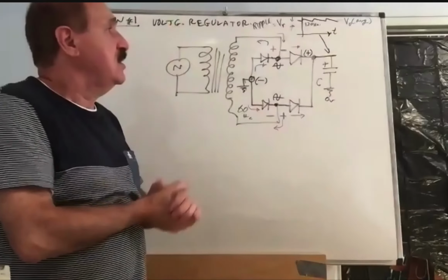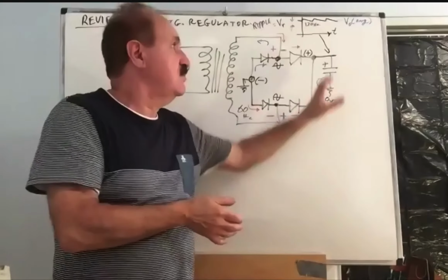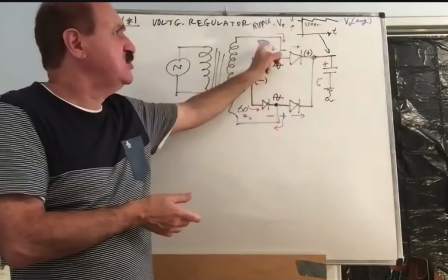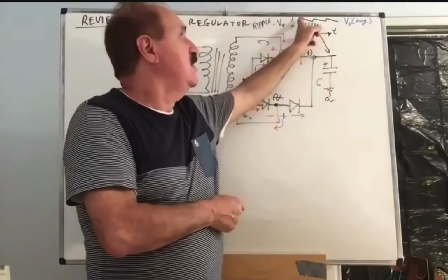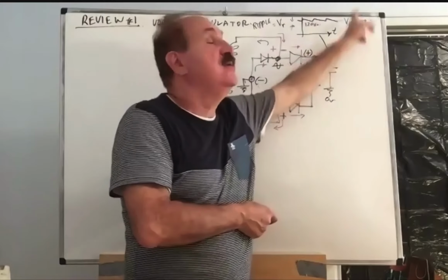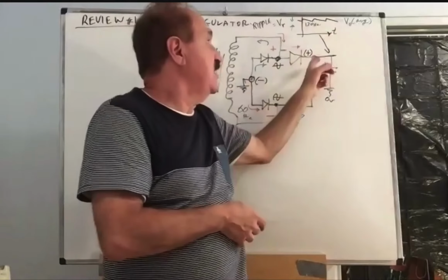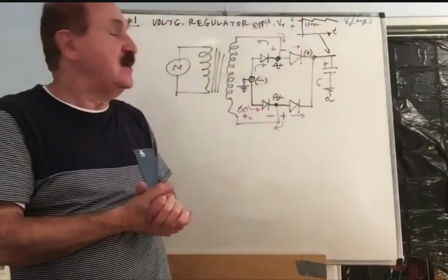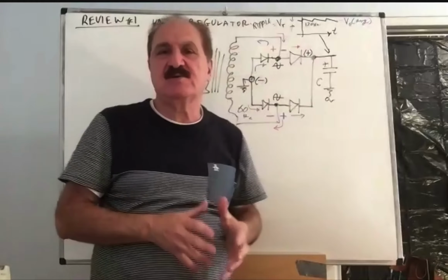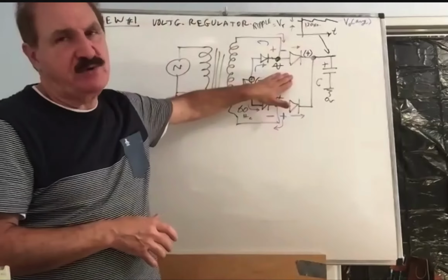So this part completes the AC to DC conversion. A capacitor and bridge rectifier, and that is the popular one. You can do this with a single diode, but then with a single diode you will get a 60 hertz ripple frequency, and generally the discharge phase will be longer, and you will require a larger capacitor to keep the ripple to the same size. So most of the time it's preferred to use a bridge rectifier.